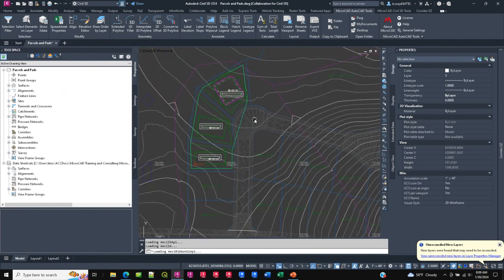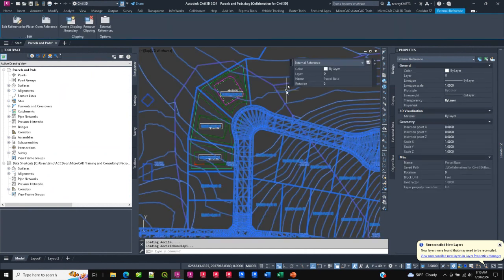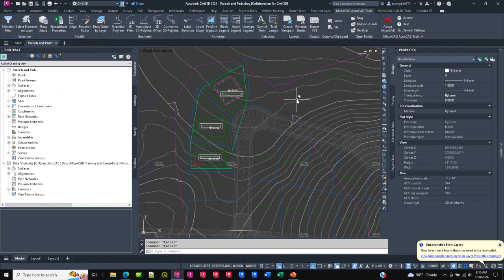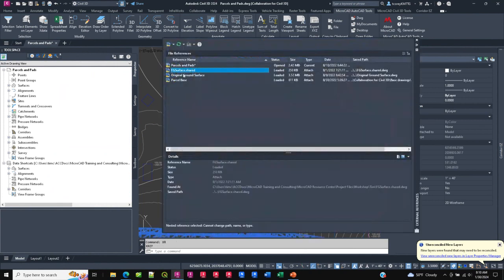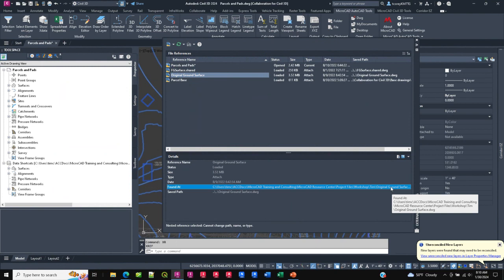Now, also, when you're working on web-based projects or BIM Docs-based projects, for sheet sets, you want to use what's called Sheet Set Manager for the web. It runs very similar to Sheet Set Manager. There are a few differences, and so you'll need to use that. XREFs are fully supported. And you can see here I've got my XREF from a path on my BIM 360 Docs.